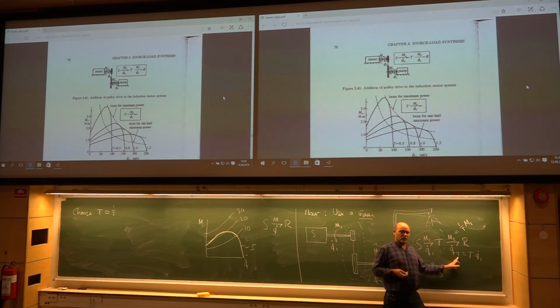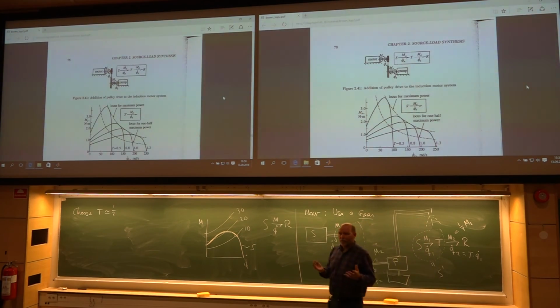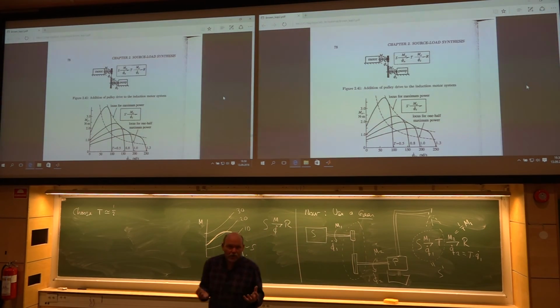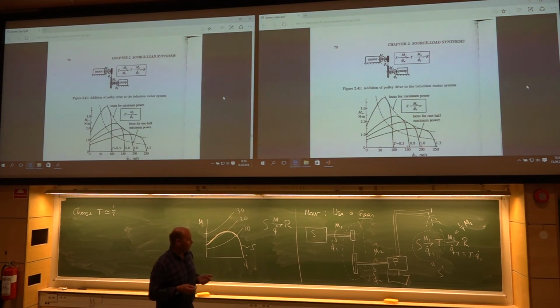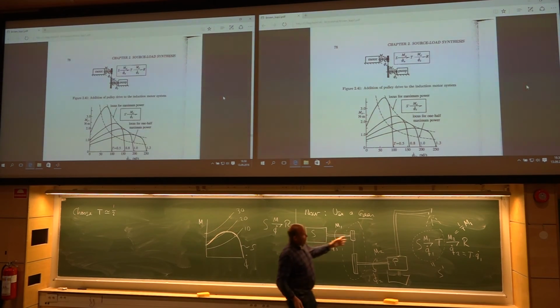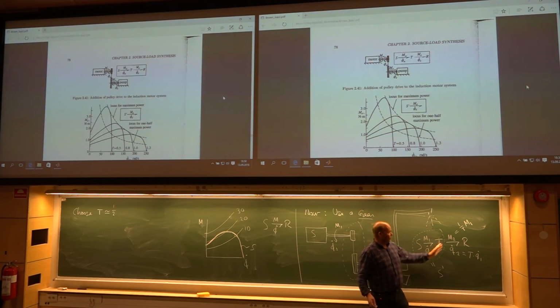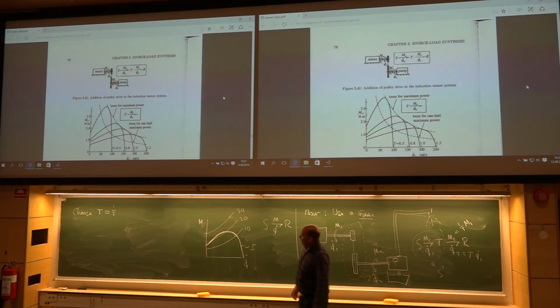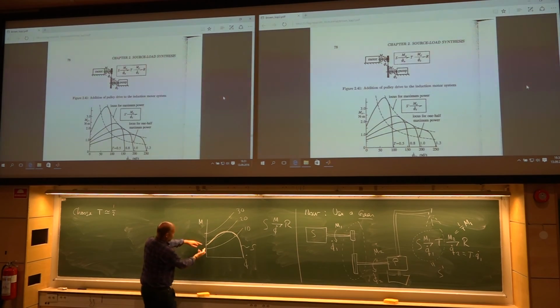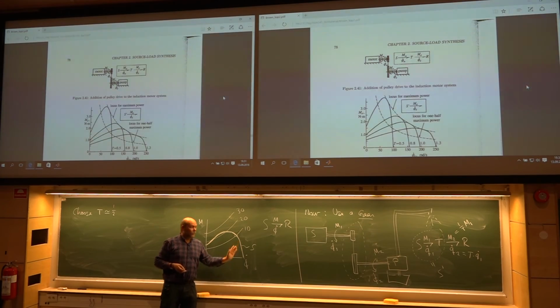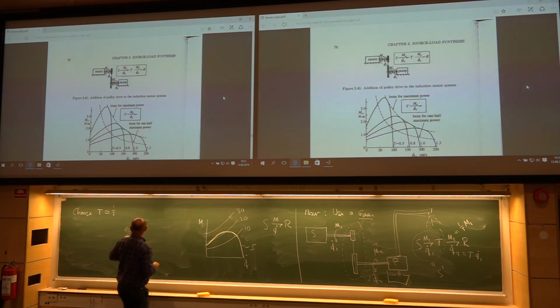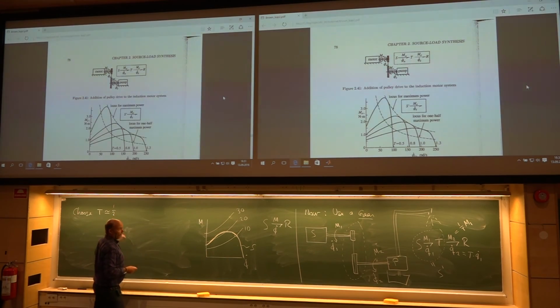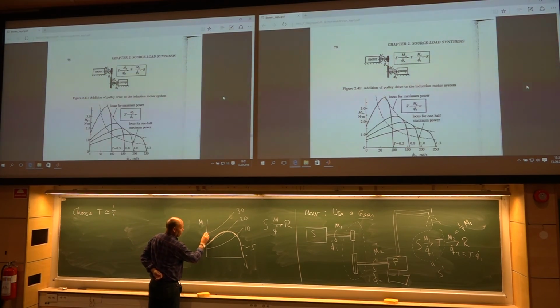What about the rotational speed? It will be halved. Of course, remember, we don't lose energy here, or get some additional energy somewhere. Energy must be constant. So it's the same energy on both sides of the transformer. So yes, I can double the torque, but then I will halve the rotational speed. So this curve, if I chose T equals 1/2, will go through this point. That's okay.